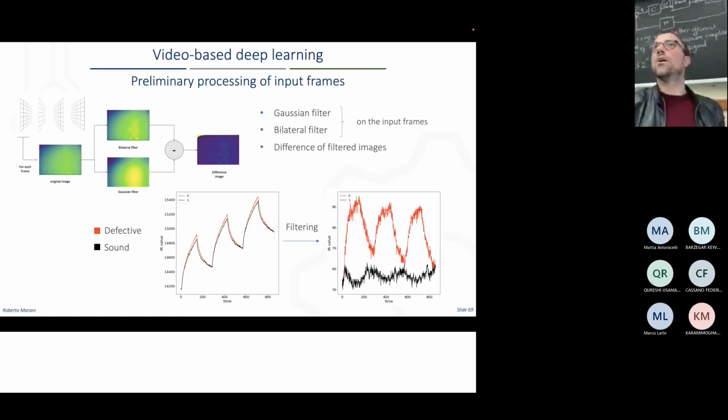Okay, so where there's an edge, your contrast is high and your sigma should be lower than the one that you use when everything is homogeneous. And there is where you want to remove noise, okay, random noise.